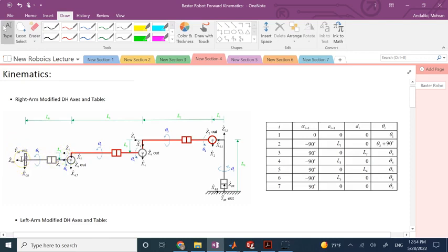Right now in this Matlab function that I have written, I'm going to neglect this final end effector frame. I'm going to go only from the very bottom of the robot, which we call world frame. It's not even this frame BR. It's below that, I'll show you. I'm going to go from there all the way up to frame 7. So at the moment, I'm not going to consider an extra frame for the end effector. I assume my end effector is frame 7, which is not really the case, but let's say it's just like a camera or something attached to it.